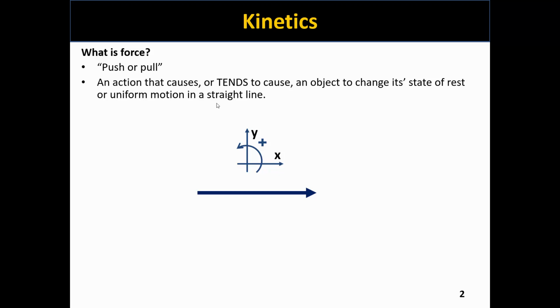And we're going to introduce some tools that we'll need to conduct static analyses. And the first one here that we'll see in the middle of the screen is a vector. And to understand a vector is to understand that a vector will sit on top of a frame of reference. And so we're going to use at this point the standard XY Cartesian coordinate system, where movements to the right that are horizontal would be positive or in the X direction. Vertical directed movements that are upward are positive Y, and counterclockwise rotations will be also indicated as positive.